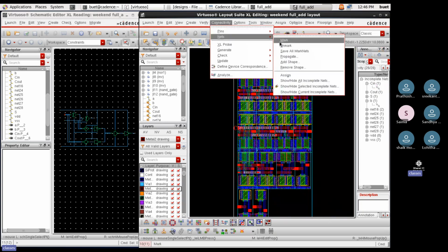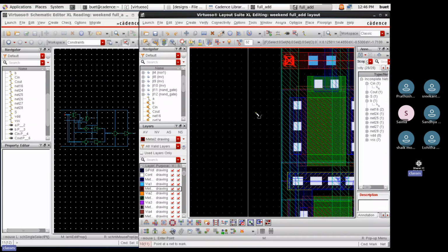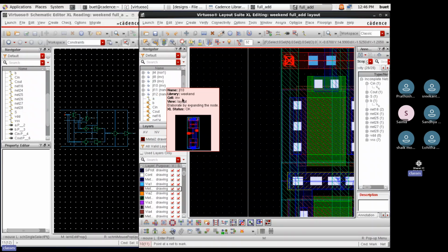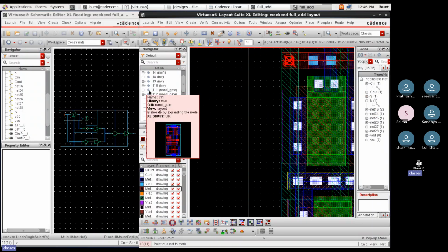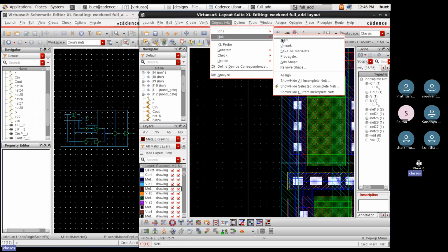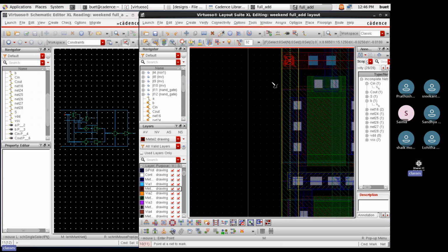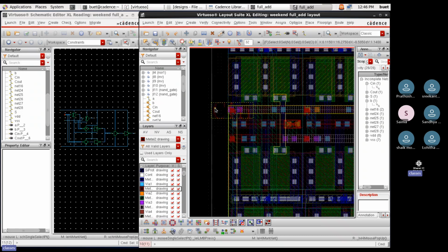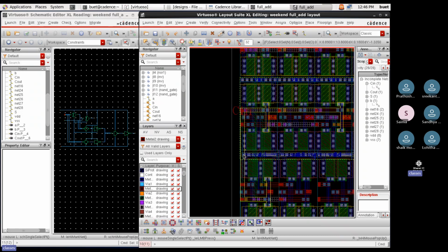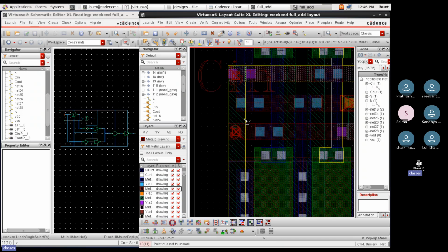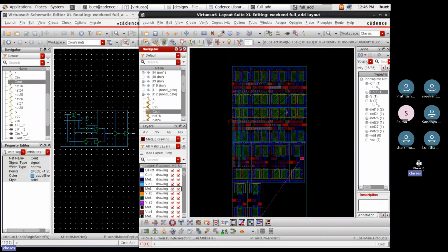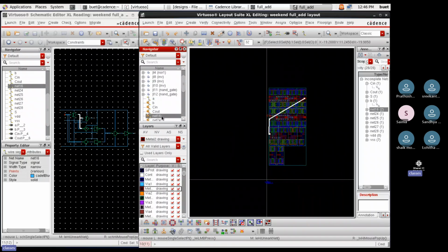For the final check, you have to go to nets and mark this one. Don't rely on the navigator and annotation browser. It is just to give you information on the connectivity. To finally check the connectivity, you have to go to connectivity, nets, mark, and then simply check whether it is connecting this or not. If it says that it is connecting properly, then it is fine. If you rely on the other one, you might for sure get an LVS issue. Again, for the C out is outside, no need to worry for this one now.